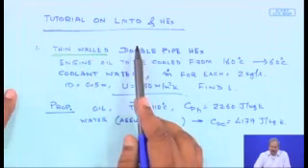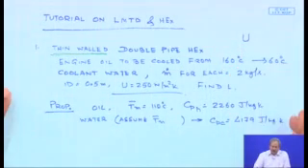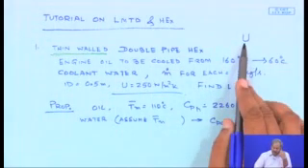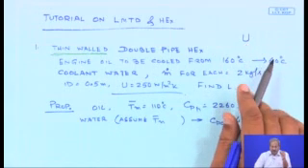and outside convection coefficient. I forgot to mention that we have also introduced the overall heat transfer coefficient U, which is just the algebraic sum of the resistances provided by the inside convection coefficient of the tube, the thermal conduction resistance of the tube, and the resistance provided by the outside convection from the outside of the tube.